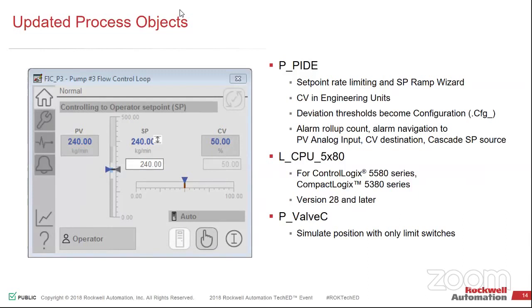One of the things I came up with is when you launch an L8, the LCPU option, that is a block that tells you all of the information. The task monitor tool, if you've ever used that, that information was part of that LCPU. It was a little add-in graphic so that on the HMI, you would be able to see the memory usage, the CPU usage, the connections that you have on a processor. The L8 broke it from the old system because they embedded all of that information into the web page. So with this new update for the process objects, they brought that back and it's specific to an L8 style controller because of the fact that it's a quad core and things of that nature.